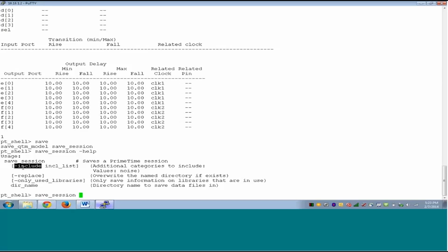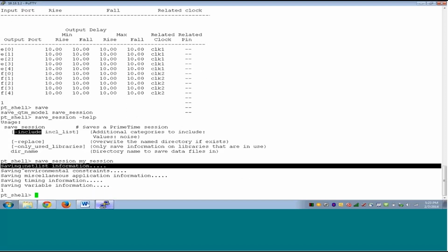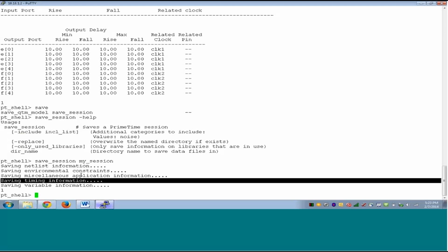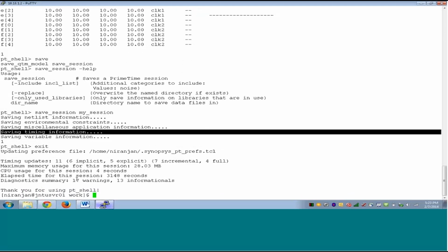So I do a save session, and I give a name called my session. It will save netlist information, environmental conditions, timing information, and all those. Right now, I exit it. I again open PrimeTime.